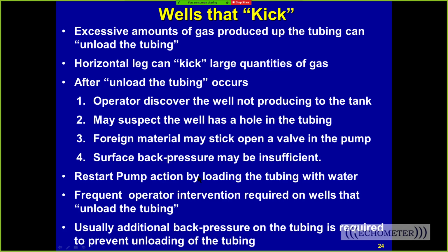So you can restart the pump and load it with water, and it'll just start pumping, because now you have a discharge pressure on top of the pump and intake pressure on the bottom. It'll start pumping, but that takes time and money. So John found that you could actually just start shooting a fluid level down the tubing with it pumping, and watch as the liquid level built up toward the surface, and see that the pump's pumping, and not have to call the truck and waste that money filling the tubing back up with water. So that's a practice that he adopted.